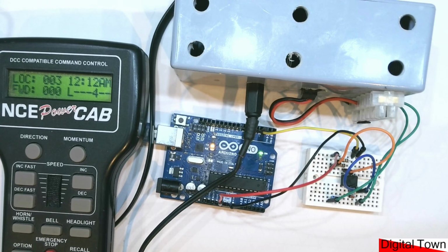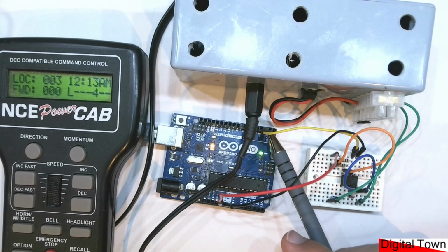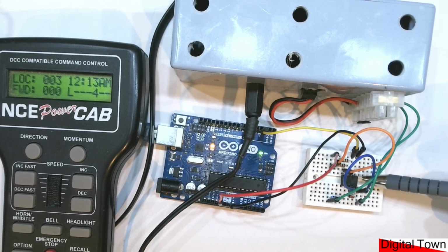So going back to the webcam, this time I have my model railway DCC controller, and here I have a circuit that allows me to read the DCC signals that are being passed from the DCC controller, and that information is then being passed to pin 2. This is an opto isolator here. That's because this system is running at, what is it, 16 volts, something like that, and my Arduino will not like 16 volts. So this circuit just makes it into a signal that the Arduino can accept.